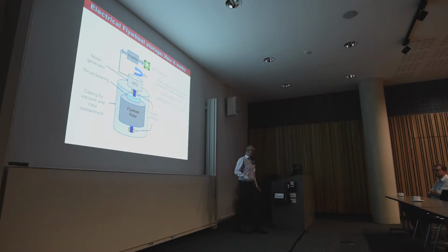So a flywheel essentially stores energy with a rotor here, which stores energy. Very simple equation, half I omega squared, but actually the usable energy is not that, because if you've got an electric machine, you've got to run this between a maximum and minimum speed. If you drop your speed right down, the torque goes, well, eventually to infinity. So we have to run between two speeds.